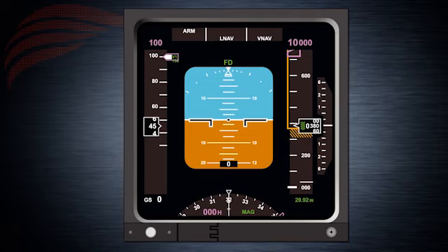The first type of display and commands we'll talk about is the flight director. The flight director is essentially an FCC data-driven display on the primary flight display, or PFD. Some call these the flight director bars, but they can also be displayed in a wings format. Depending on the mode selected from the MCP, the FCCs send the information through various components to then be displayed for the pilots to follow.